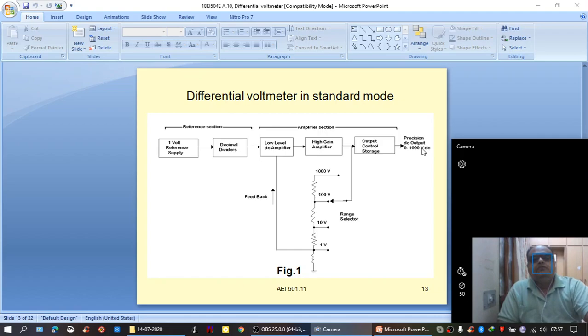When the output voltage once again becomes 1000, here you will get some value of E1 once again back, and here it would be some VR, and this minus this will have some difference voltage, say ED. As long as the voltage here is ED and the voltage here is E1, output voltage would be 1000.